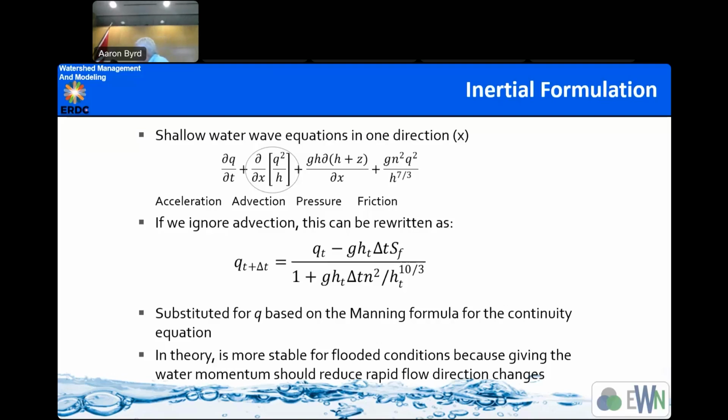So solving those explicit equations, you need a solver, like PETSc or something? No, it's explicit, not implicit. That means you do not need one of those fancy solvers. We don't make a big matrix to solve it. That's an implicit solution, which we do for the subsurface. We're not going to talk about subsurface solutions in this class. This is all explicit, and in general, you solve hydraulics problems explicitly. It just lends itself to it.